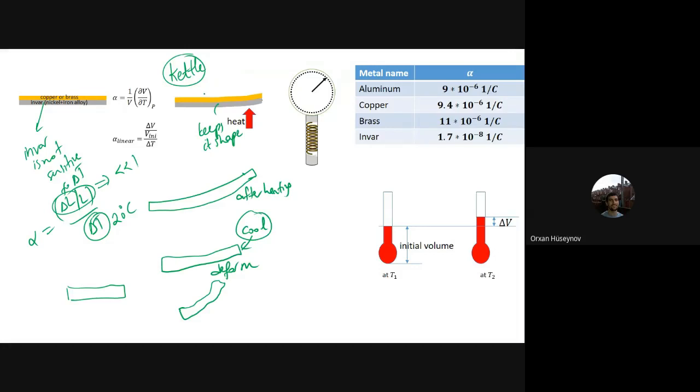Okay, the electricity circuit breaks. Why? Because you have this combination inside your kettle. When it is heated to 100 degrees Celsius, this one deforms, or elongates, and therefore the contact breaks, and you have the electricity cut off. Okay? That is the reason.